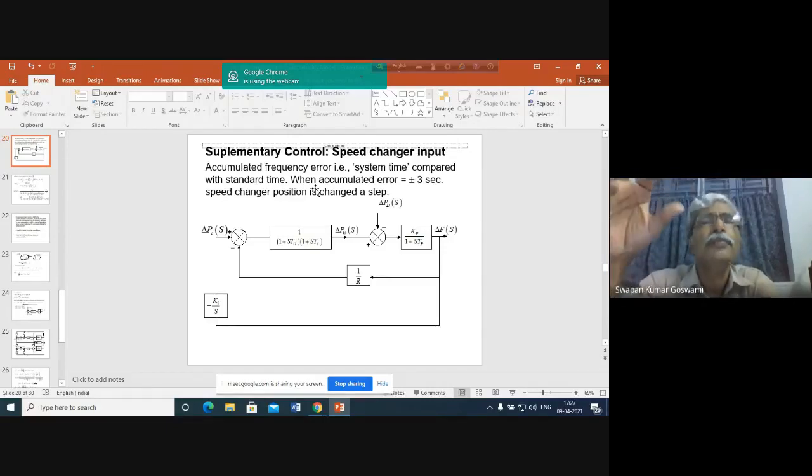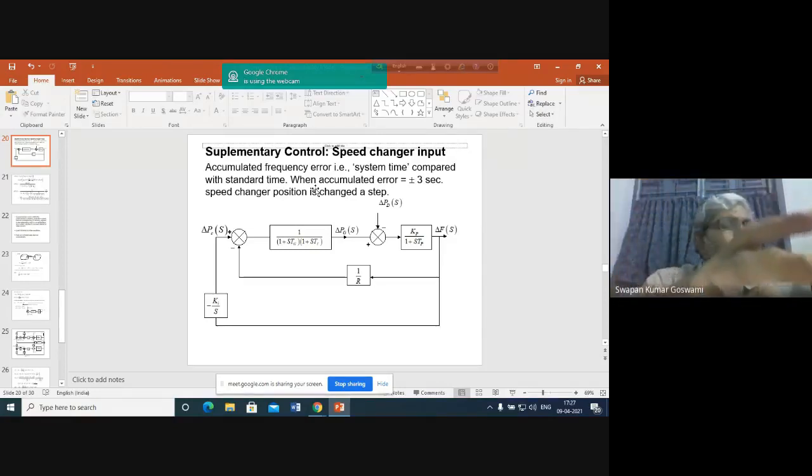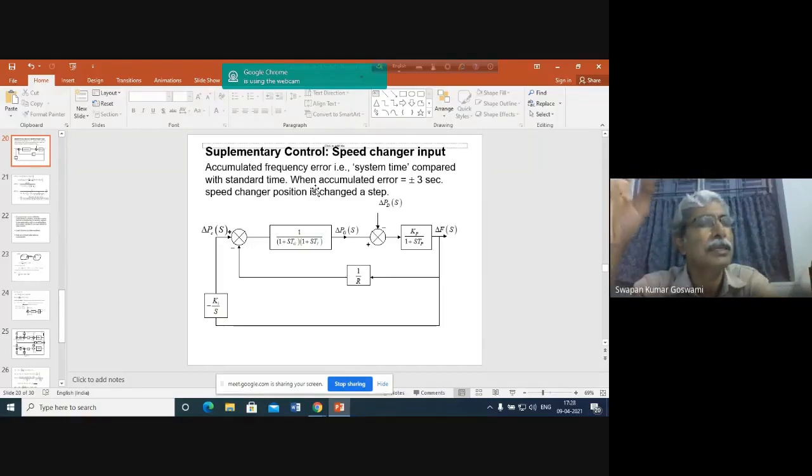Basically, if you draw power when the frequency is below normal, then you have to pay more price, and that price is a penalizing price. But if you inject power during that time, undeclared injection, obviously you have not declared it previously, then you will be getting a rewarding price for that, because you are helping the system in restoring its frequency.